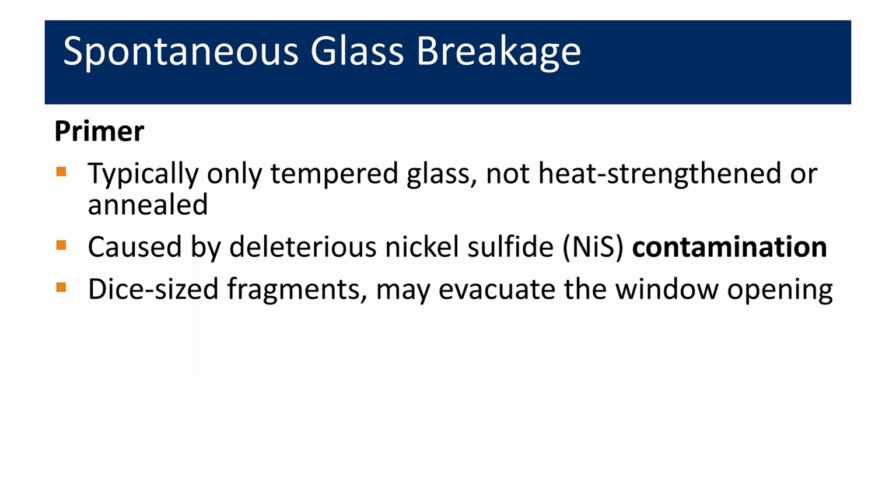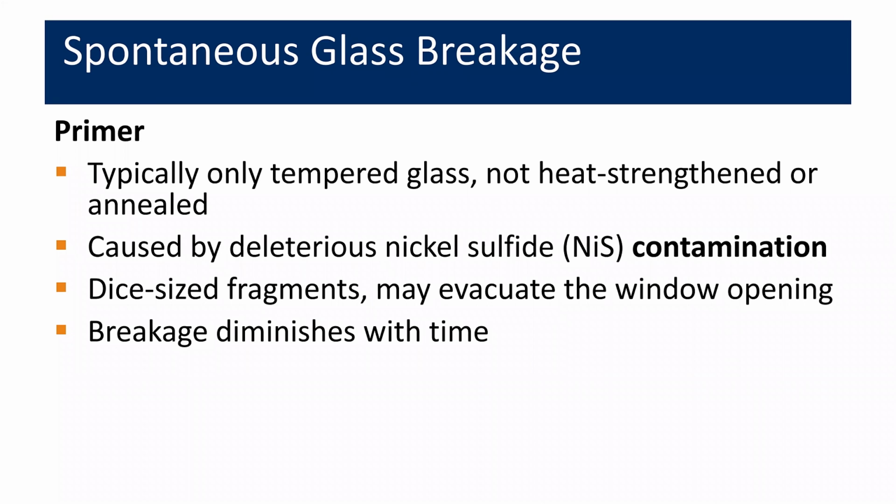The glass, when it breaks, typically breaks into some dice-sized fragments that can readily evacuate the opening. This phenomenon diminishes over time. There's a variety of published guesstimates really on how long it takes for it to subside. And the usual time frame is about 8 to 10 years following installation, though exceptions obviously do occur.